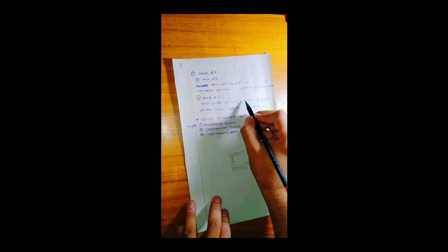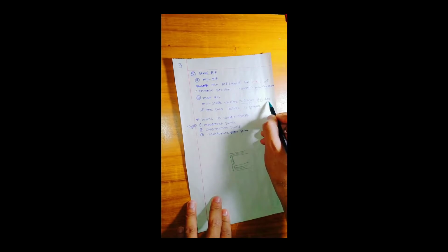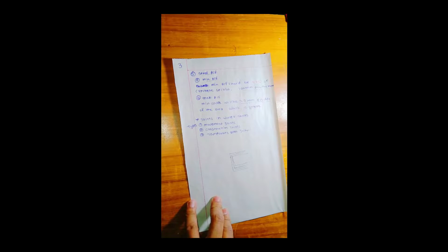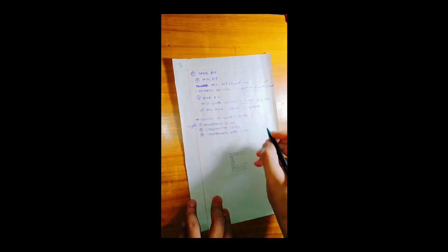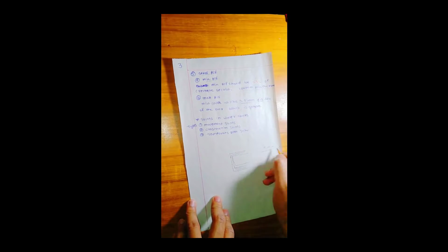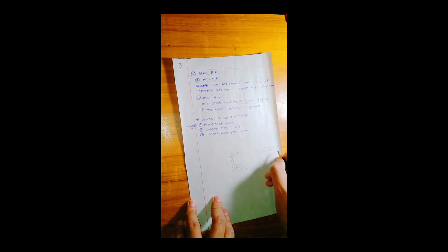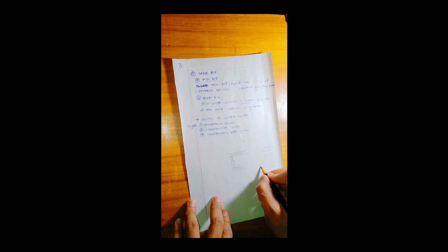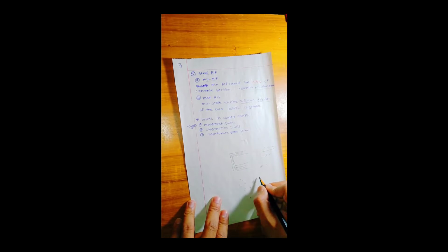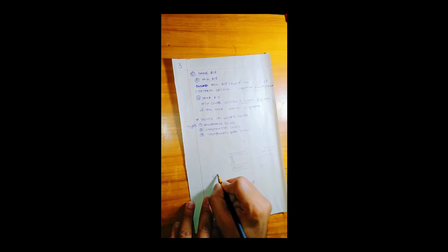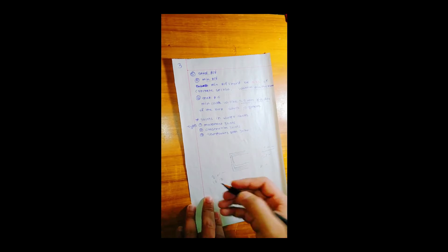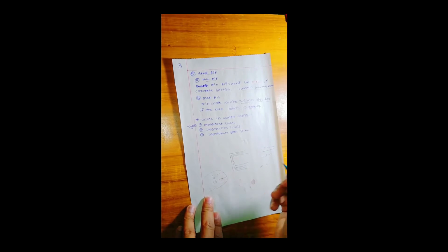Maximum reinforcement, minimum cover will be 25 mm or the diameter of the bar, whichever is greater. Generally in a slab we take the cover as 50 mm, but in a water tank we have to take 25 mm or the diameter of the bar. Generally the bar diameter used for a water tank is 8 mm for the tying members, 10 mm or 12 mm. Again we will see this in design.